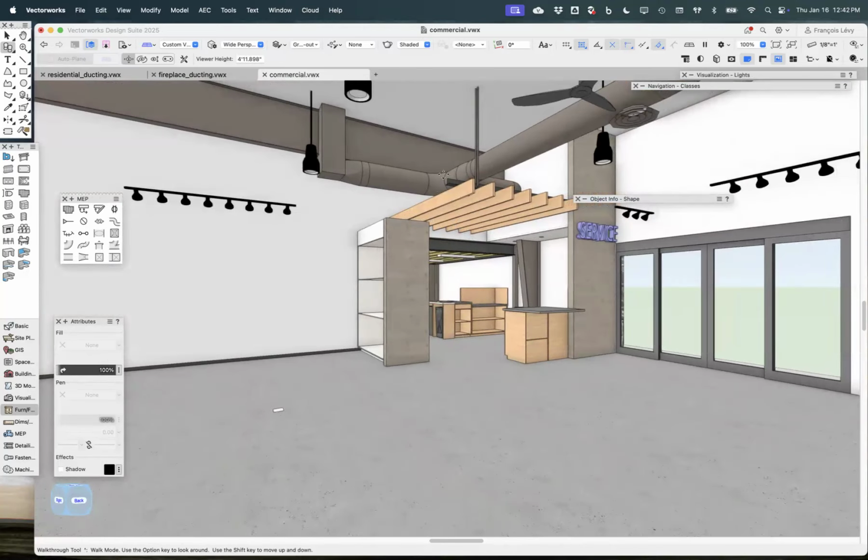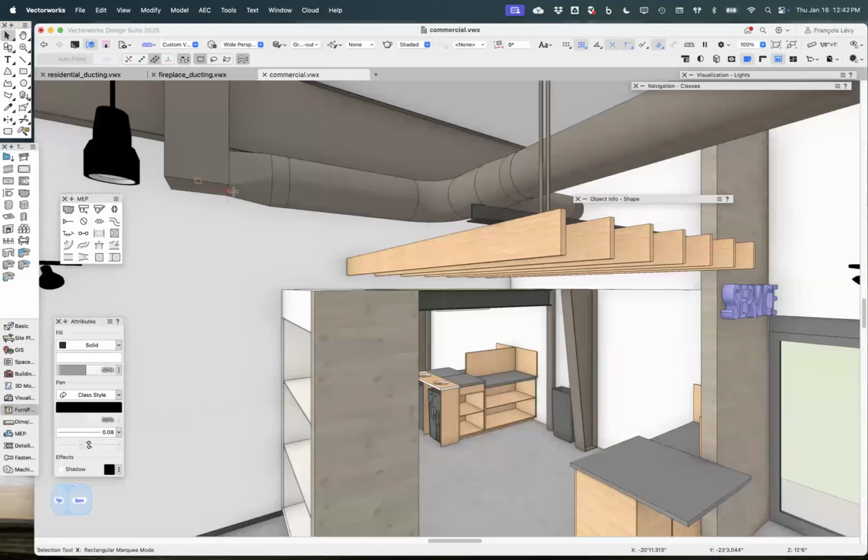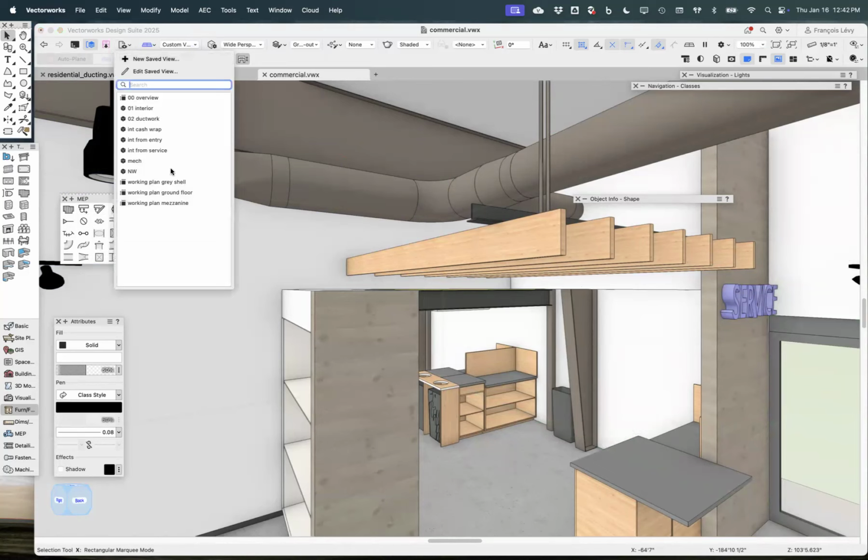And then all of this that you see, like this transition from a round duct to a square duct, where we've got this vertical duct coming off of the rooftop unit, and then transferring to round duct for a better appearance inside. All of that is based on using these components from the ducting tool, the vertical elbow, the vertical duct, the horizontal duct, and so on and so forth. So that was pretty cool.